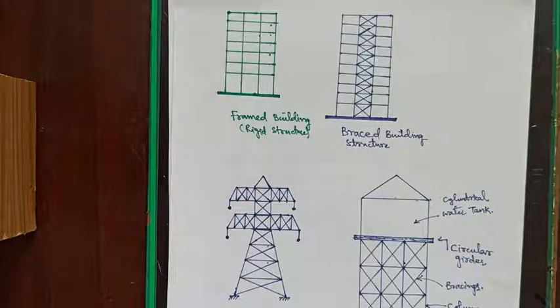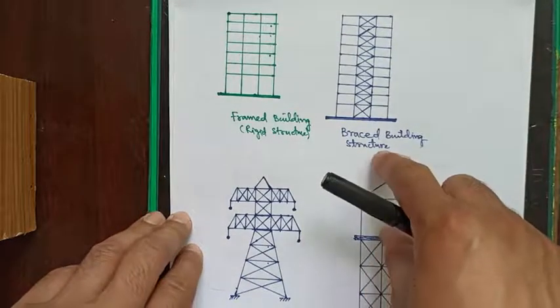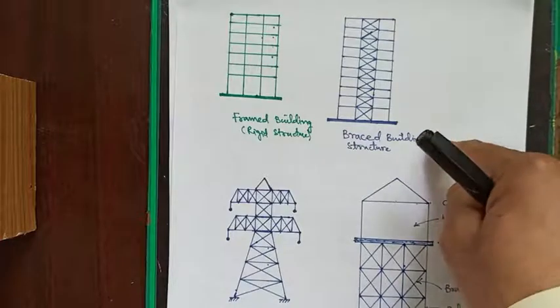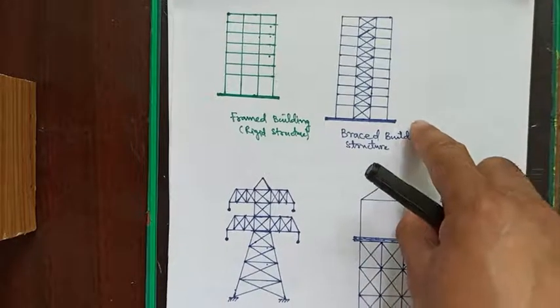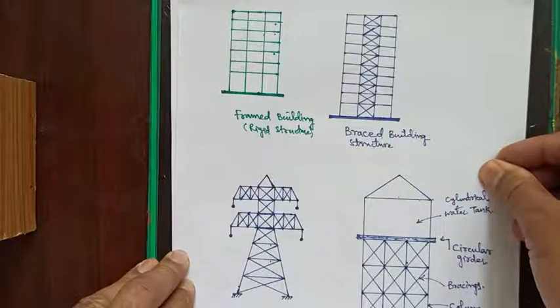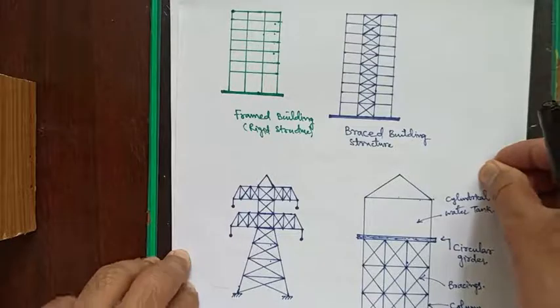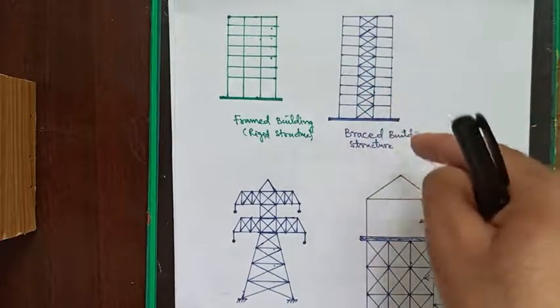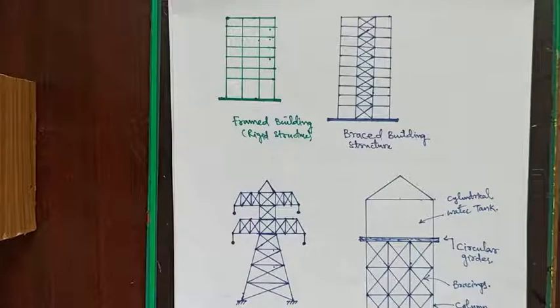Most of the steel structures belong to the category of braced and rigid frame construction. They essentially consist of regularly spaced columns joined by beams or girders. Secondary beams span between the main beams and provide support to the concrete floor or roof sheeting. In the case of braced frames, the beams and columns are designed to resist vertical loads only. The connections are designed as pinned. So braced frames with pinned connections and vertical bracing systems offer a very cost-effective structural solution and are the most commonly used structural systems in buildings.